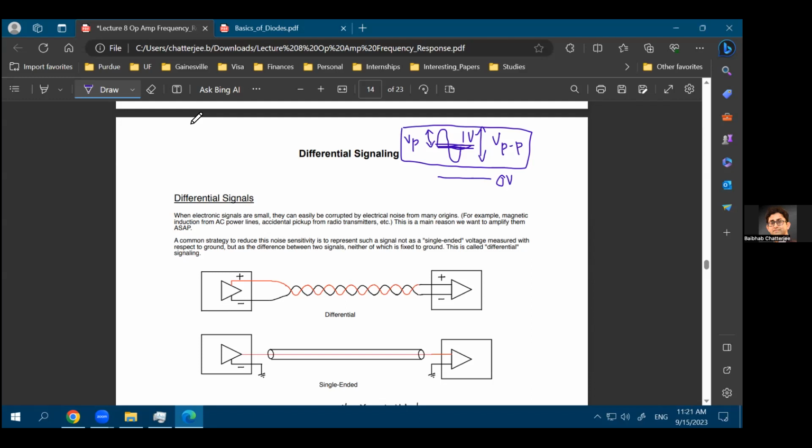That you always have to think about with the difference of two signals. Whenever we talk about single-ended signaling, we take the difference with respect to the ground or with respect to the reference that we have established. So for any circuit, let's say I'm just drawing rectangles over here to represent circuit components, but it could be resistors, capacitors, other things as well. You have to define a reference point, and let's say you define that reference point to be a ground.